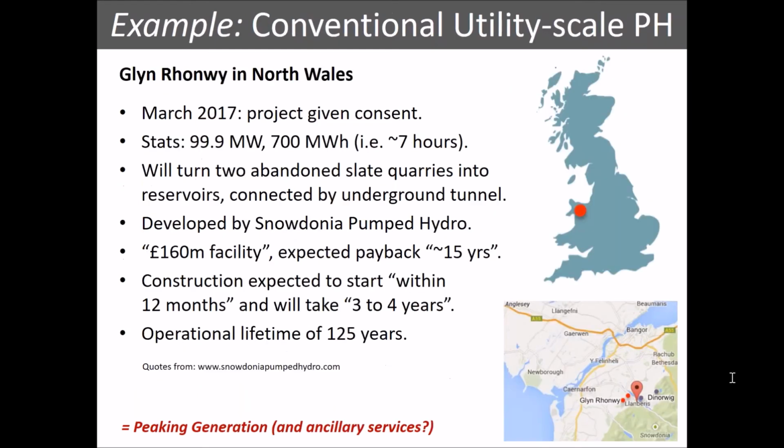And again, just before someone screams at me that it's not all about batteries, conventional pumped hydro, this is actually the first pumped hydro scheme in 30 years, I think, here in the UK to be given consent for construction. Again, similar size, 99.9 megawatts, which is interesting, so about 100 megawatts. Much longer time frames, 7 hours of storage. Again, it's using abandoned quarries in this case, so 2 reservoirs, you pump water up and down between them. Much different business prospect. So they're expecting payback over 15 years. Now, battery developers I've talked to are talking more in timescales of a few years.